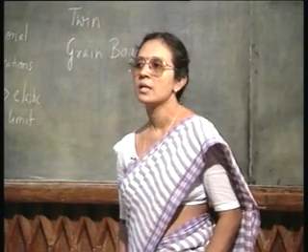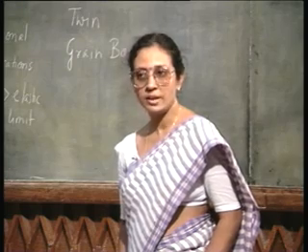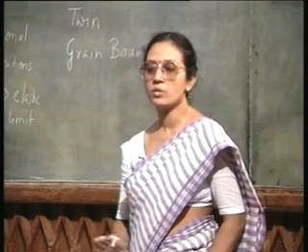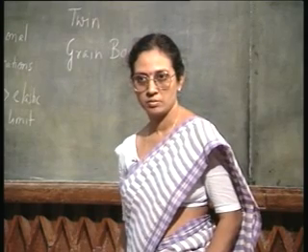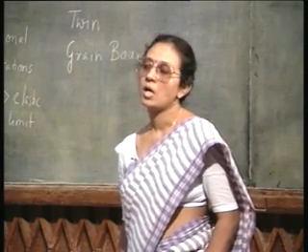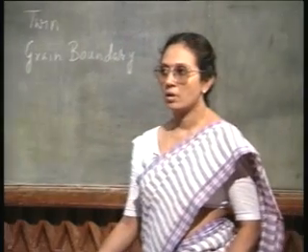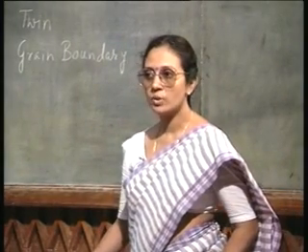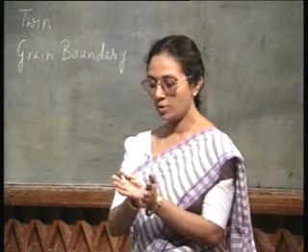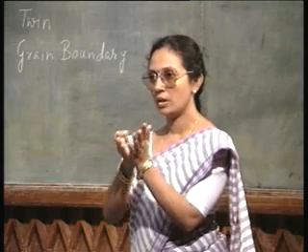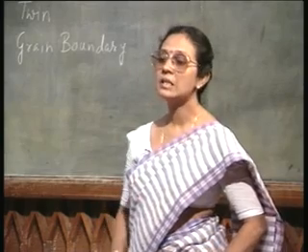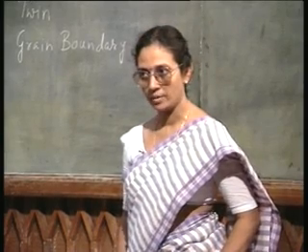It means two parts of the crystal, they are in intimate contact, but they have some orientation with respect to each other. This is called a twinning. So, both the parts will have some crystalline orientation, but in between you are having a change from one crystalline orientation to another. It is not a real single crystal, that is twin.